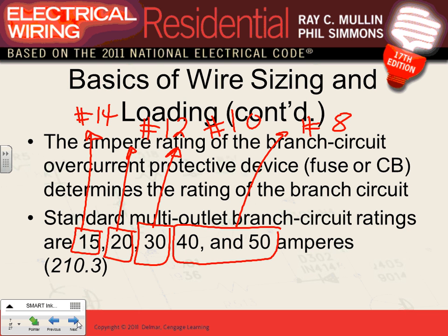So can I put a 15 on a 12? Yeah. Remember, can you guys see that? These are min. All these are min. These are max. I need you to understand this from the get-go before we start the commercial. With the overcurrent protection device, we talk max. With conductors, we talk minimum. What does that mean? I can go higher than the minimum, but I can't go higher than the max.